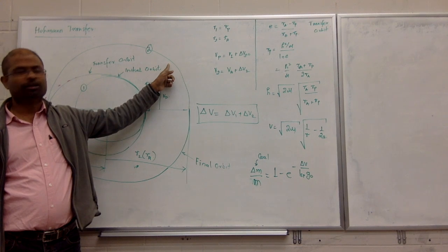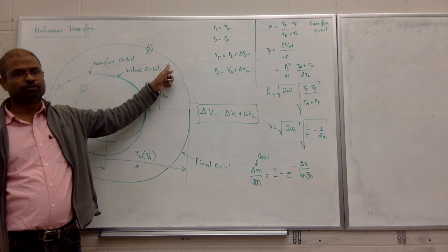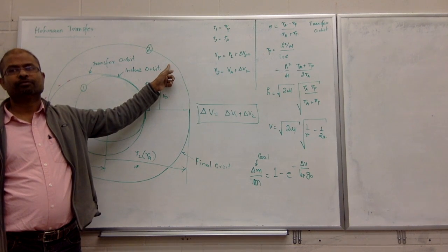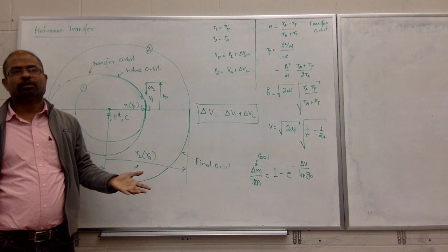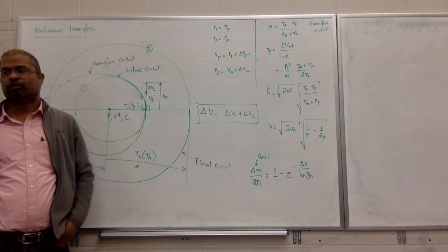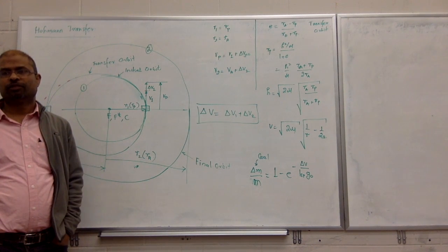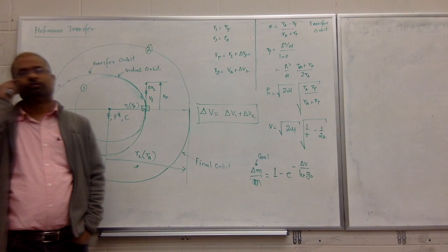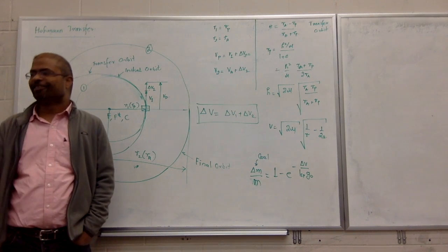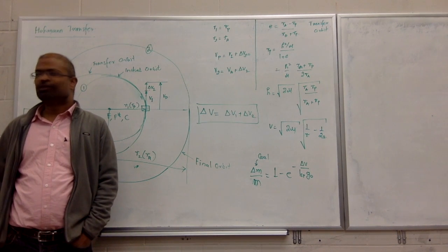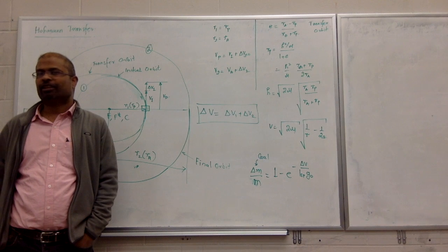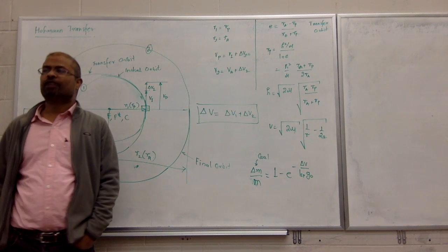No, RP is not the radius of the Earth. The 2000 is altitude. You cannot get into a 2000 R. If R is 2000, where are you? In the Earth. 2000 cannot be RP, RA, anything like that. You're inside the Earth if R is 2000.